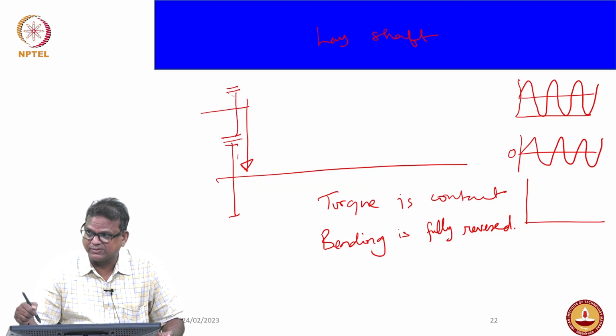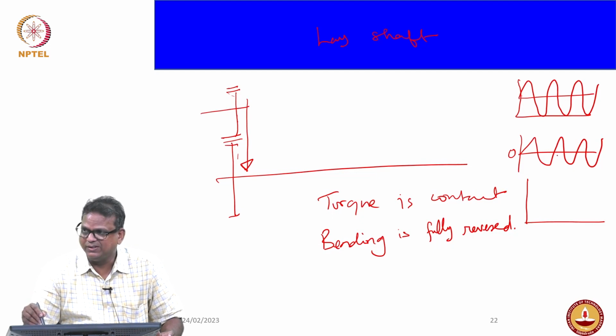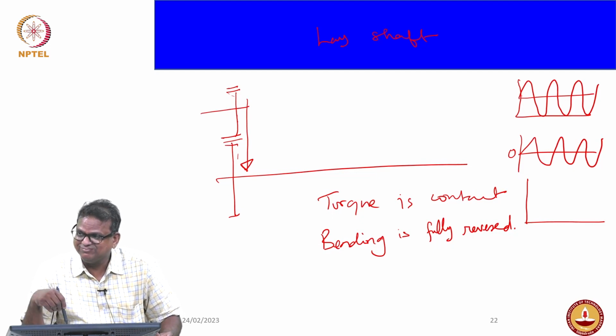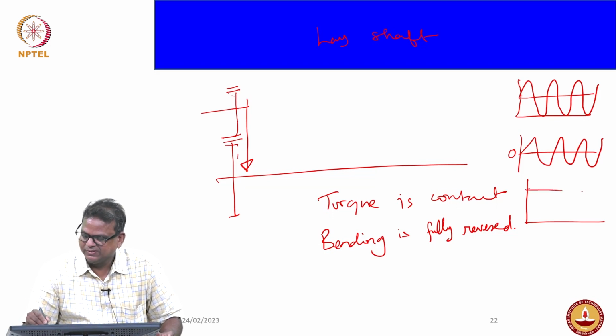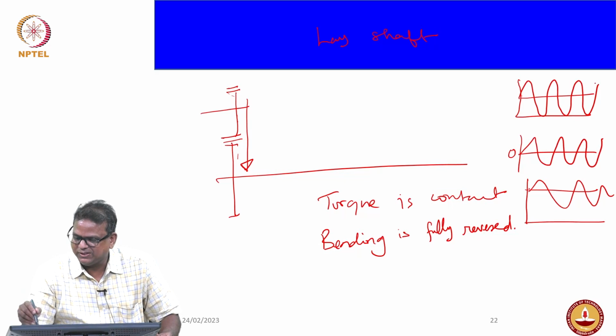There are 3 things in the fatigue load aspect, right? Which one is the fully reversed here? The second one, right? So what about fluctuation? Somewhere else it will go like this, right? So these are the 3 arrangements. Do you expect the gear to be a fluctuating load? No, it won't be fluctuating, right? So it should be maximum to zero. So check all those aspects.